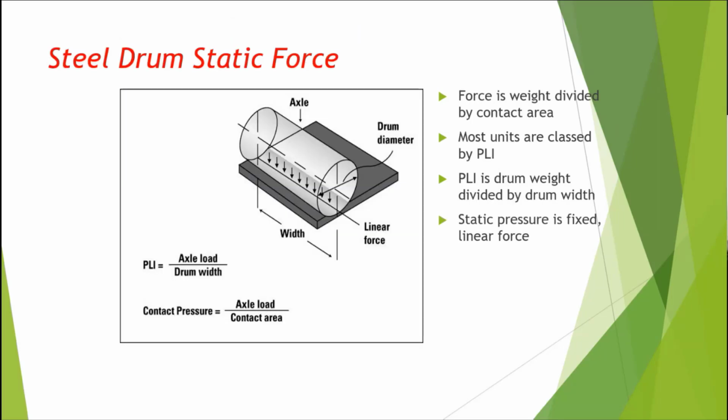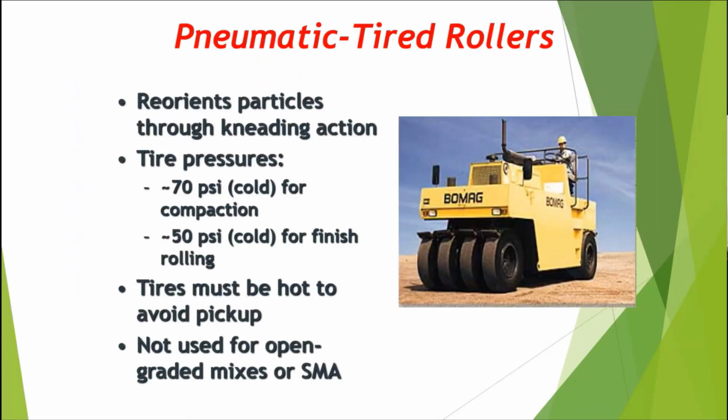Some changes, but it's all about what type of force, how much force do I use to squeeze air out of the mat. And things to remember, PLI, that's pounds per lineal inch. It's basically weight on that axle divided by the width of the drum itself.